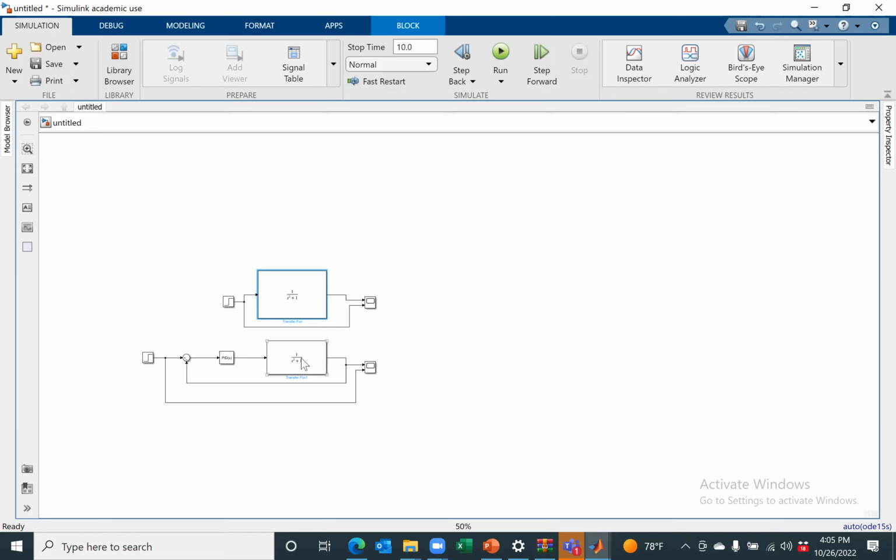So you are going to add the controller effort, which is proportional to state. What does that mean? If your mass is farther from the set point, then you are going to apply more and more controller effort. As this mass starts going closer to the set point, your controller effort is going to drop down. Everyone understood this? That is the proportional control.